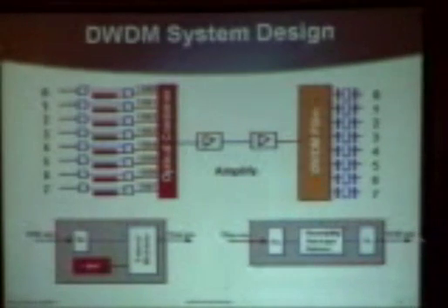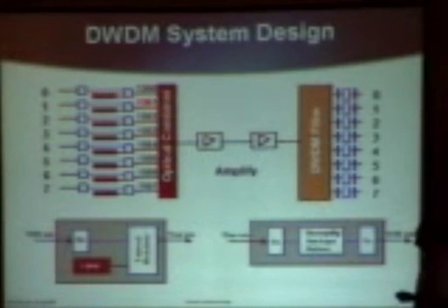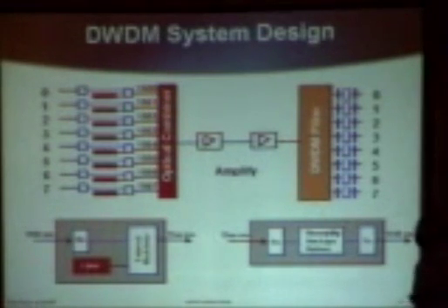So what do the WDM systems actually look like? Well, we talked about the amplifiers. The WDM systems are really just optical modulators and a combining system. This is a very simple picture. This would be 1550, 1551 nanometers wavelengths. If I'd been a little bit more careful, what the ITU does is they recommend 100 gigahertz spacing, which is actually 1.6 nanometers.